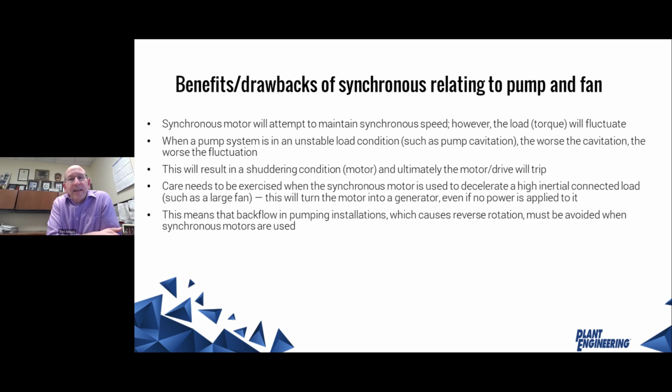Another thing to recognize is that if there are fluctuations in your system, and when I say that, not just smooth fluctuations, but quick ones that you might call cavitation or instability, a synchronous motor might need some other things in the system, such as the addition of a resistor on the DC bridge, because otherwise it becomes a generator pretty quickly. So there are some things like that to consider, particularly as it pertains to deceleration. You don't want to turn your synchronous motor into a generator. Your drive's not going to like that. So, there are some things to consider.